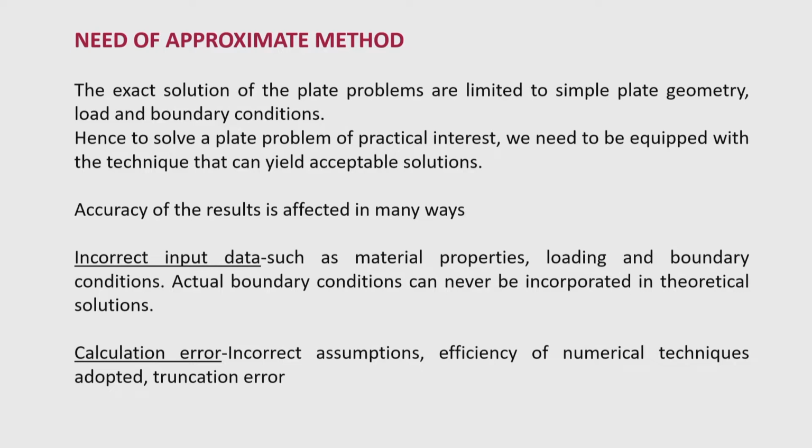Incorrect input data, such as material properties that we require in plate problems, which are usually the modulus of elasticity and the Poisson ratio of the material. For a steel plate, the modulus of elasticity and Poisson ratio are almost homogeneous quantities, but concrete is a heterogeneous material.